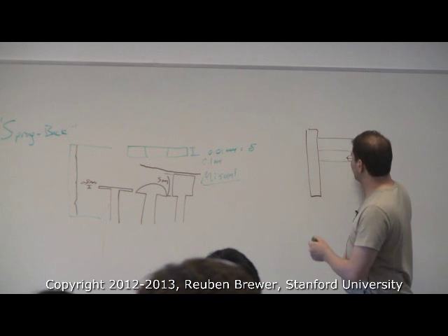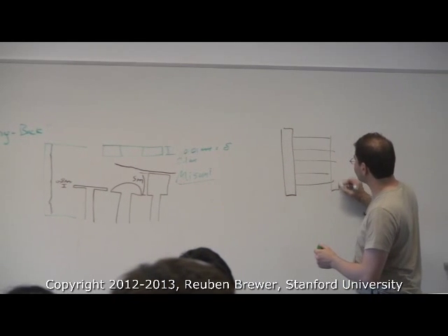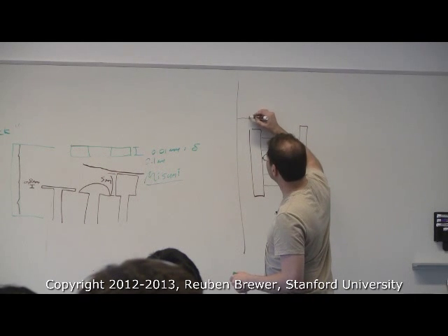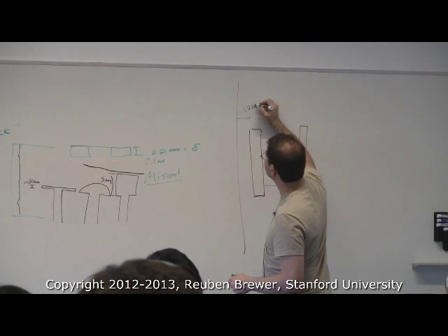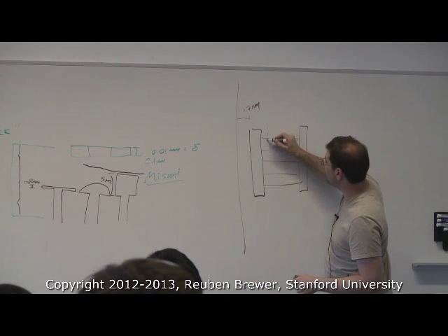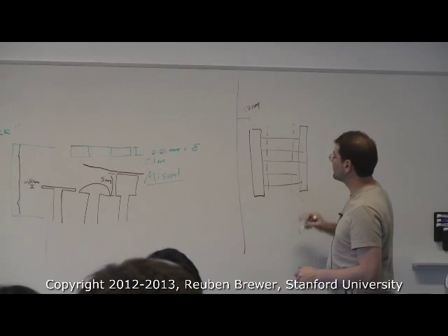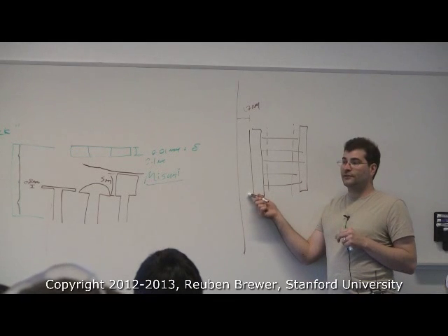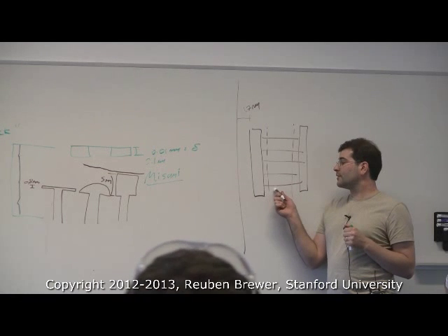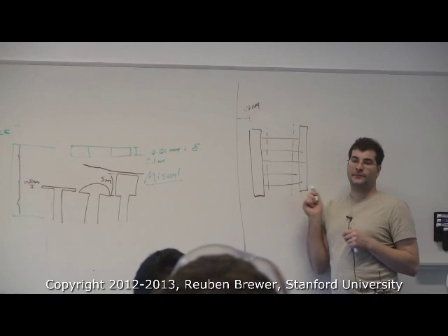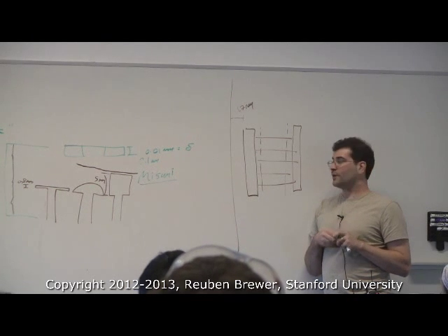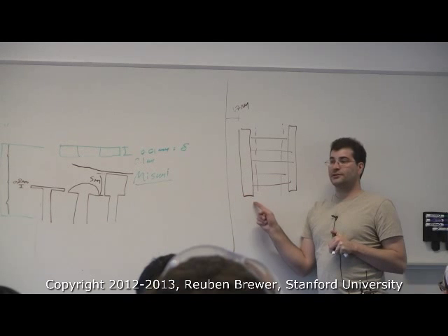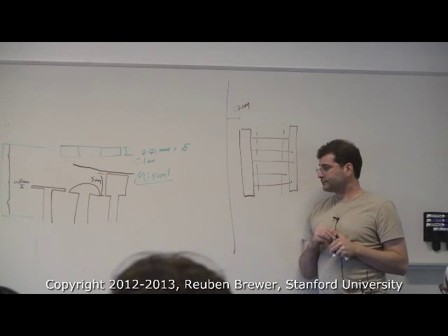So this was our little 30-tooth pulley, right? And then this was the big wall. This distance here I set to be about 1.7 millimeters, and I set that so that the belt would be centered here. What most people did was install it willy-nilly to whatever it was, and then the belt was rubbing on one of the flanges. The only way that you would have noticed this is if you had opened your CAD up as assembling and started measuring these things while assembling.